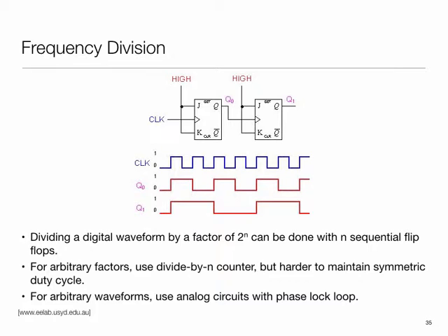Each time you detect a rising edge coming in, you send out 2 rising edges or something? Yeah, but where would I get that from? How would I get a shorter time period of it? Yeah, PLLs. So anyone else knows PLLs? Heard that term. Okay. So firstly, clearly, we talk about processors operating at gigahertz, all right? So obviously, we don't have gigahertz type crystal oscillators, right? So we achieve those things by multiplying the clock, okay?